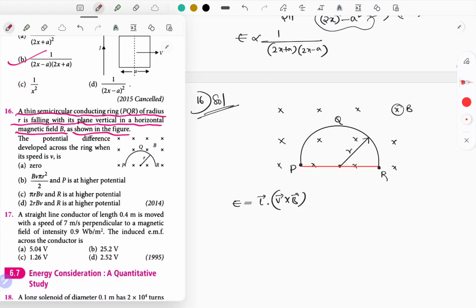First of all, decide the direction. Forefinger indicates direction of magnetic field, thumb indicates direction of motion of the conductor, and middle finger indicates the direction of current flowing through the conductor, isn't it? Yes or no? So let's decide the direction. This is how current will flow, right? And that is the displacement we should consider.